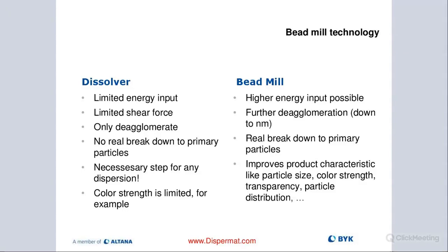And then obviously some people think, oh, I'm working with the dissolver. That's all I need to do. I can stay there. I don't need to mill. Well, but then you're going to have problems with the product quality, right? So we talked about that earlier. It's really important to get the best looking product and performing product. You really need to bring the particles down as low as possible, primary particle size ideally, and that will give you the best looking and best performing product.